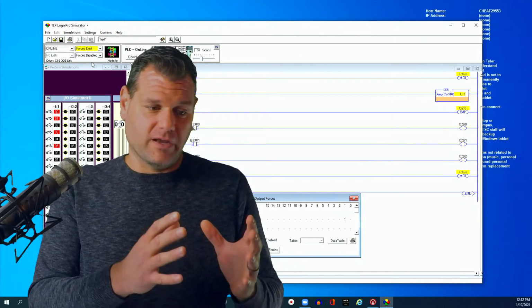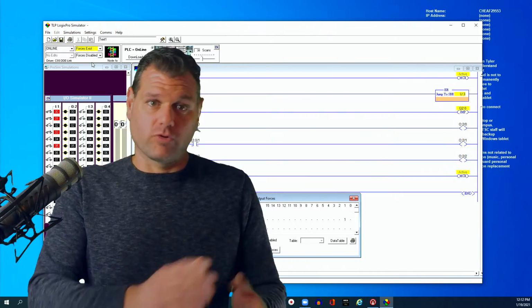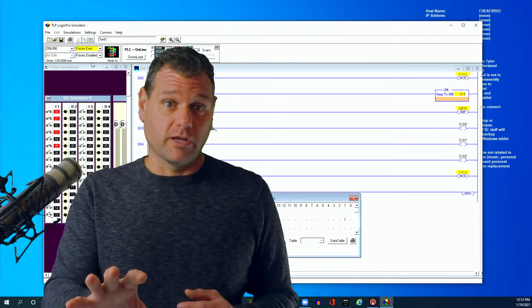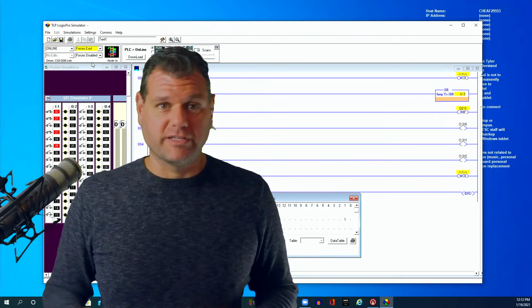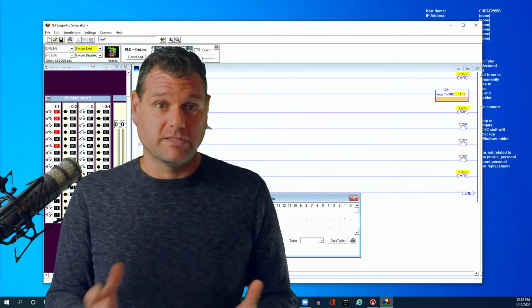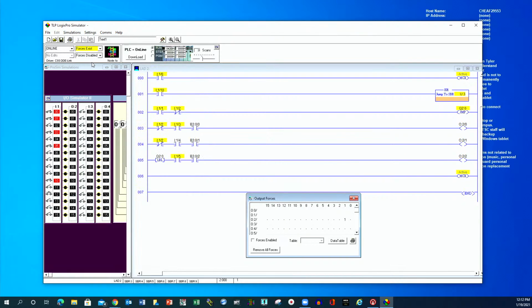You're telling it that a safety switch is being ignored, or whatever the logic is that says this thing should not be running, you're telling it run. So it's asking you again. It's like Windows saying, "Are you sure? Do you want to save this? Are you sure you want to delete this file?" It's that version of that. Okay, so basically, forces do exist, and then I have to go down here and say enable forces.